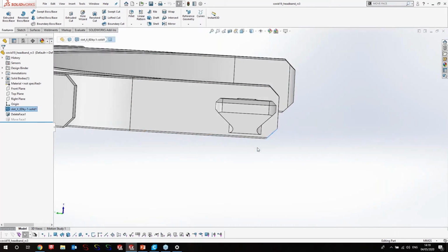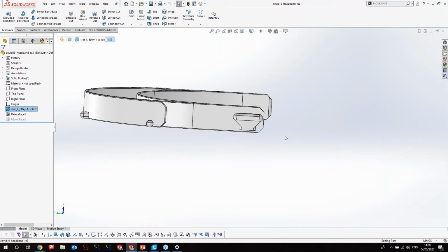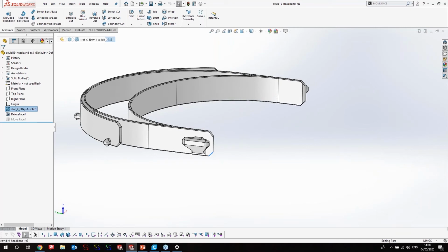And what these allow the design to do is make it a little bit easier to take them off the build platform. If you do have any chamfers or any angles like this, it means you can get a scraper underneath just to get them off a little bit easier. So it runs into a slightly different aspect of the design, but it's also making that whole process a little bit smoother, a little bit quicker, and a little bit easier.